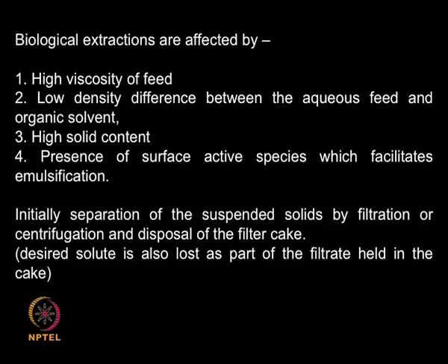So the two liquids separate out nicely and we can remove the bottom and the top layers independently of each other. High solid content: as you know, fermentation broth contains a large number of salts which you add, so there is going to be a lot of solid present. The solids are going to hinder your extraction.